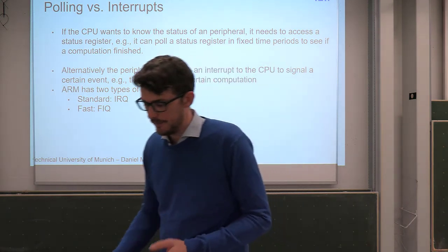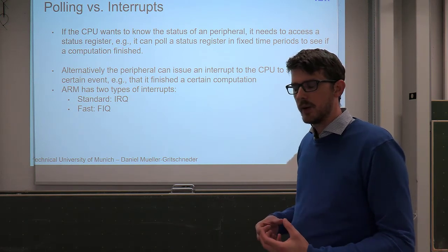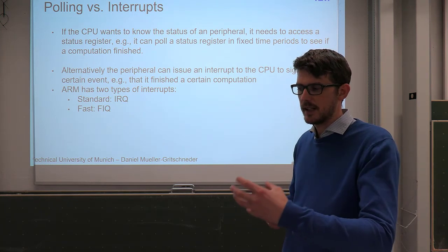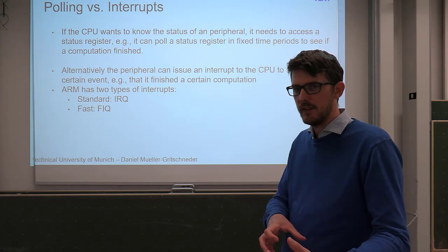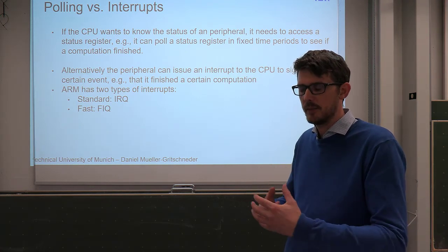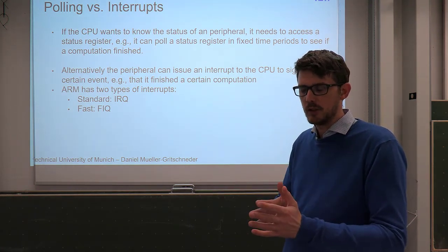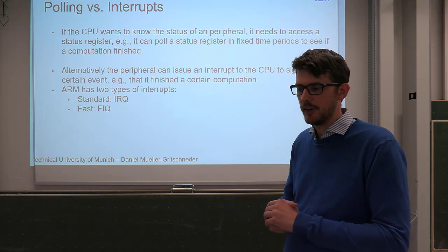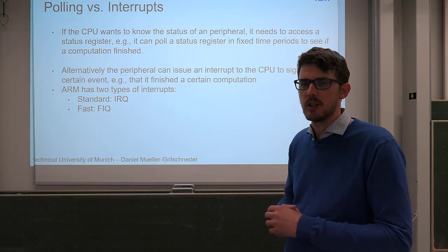OK, great. So I hope this example with this hardware accelerator gave you an idea how you can connect some arbitrary hardware with your software and hook it up. And you see that this hardware-software interface always has a software part, where you're writing this driver. It has a hardware part where you're taking the device and hooking it up with your system bus, so it becomes addressable from your software. And basically the interface between the two is this register list and bit field list, where you have specified what kind of data from the device is accessible via which address.